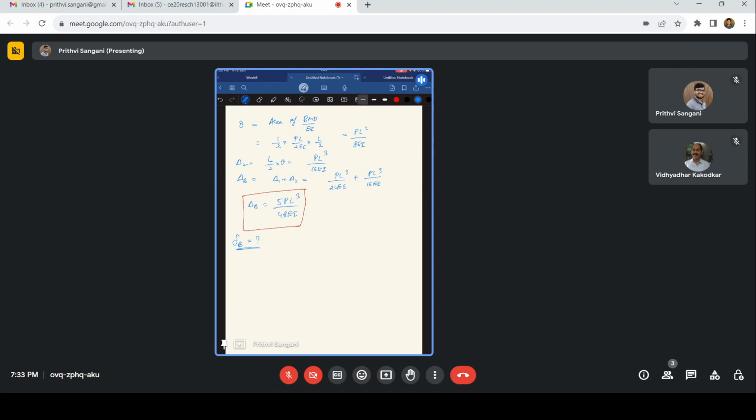So we need two compatibility conditions. What are those? Let us formulate that. The first step is breaking down the indeterminate structure into determinate structures. How can I do it? In this, I'll choose the cantilever, because it is easy to solve. Cantilever beam plus, now my two redundant forces are going to be a vertical force VB